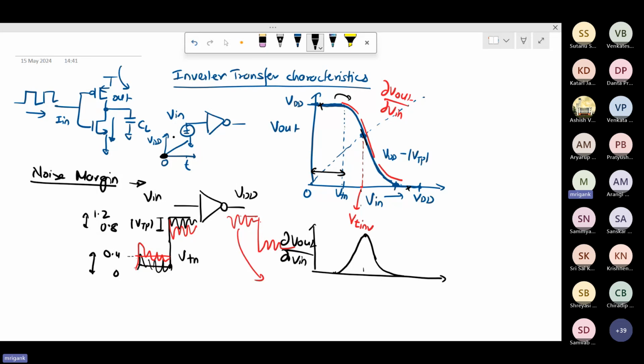So that's why we say that in digital circuits, we can handle more VDD noise, supply noise can be significant, but still the circuit will work. So 100, 200, 300 millivolt of supply noise also it is able to handle. But in case of analog circuits, we have already seen that even a little bit of noise is not acceptable because that is directly going to corrupt your analog signals because we are concerned with exact level of the analog signal. This noise margin concept should be conceptually clear to all of you.